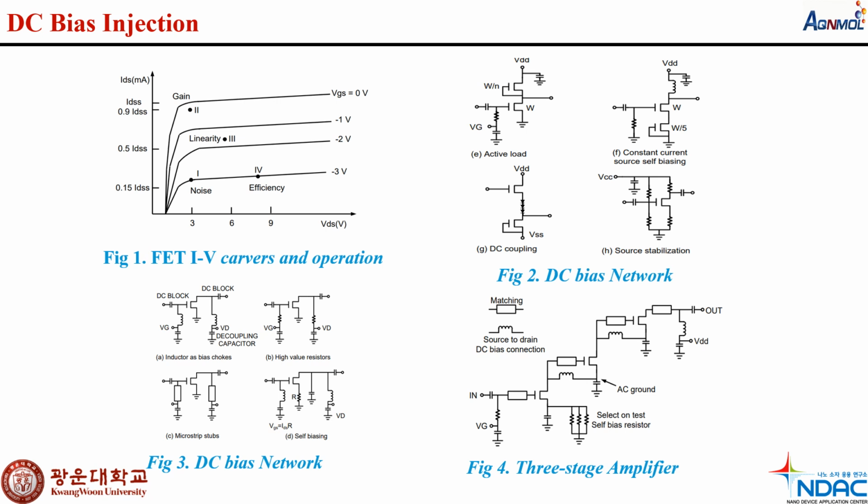The on-chip decoupling capacitor for bias might not be sufficient and an external solution may be needed for the stability.